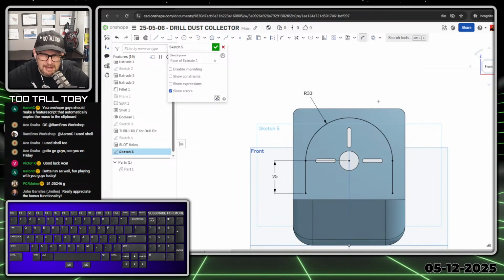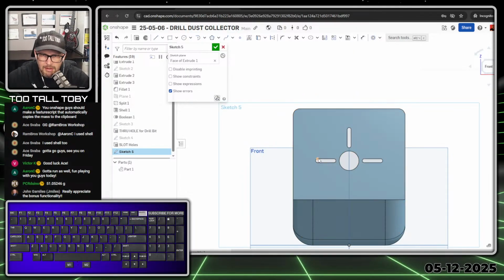One thing that I did there, I did it kind of quickly. Let me just show you this again real quick here. When I was creating that line arc line, I did the single click to begin the line, single click, move back, touch the end point, come up and over with the arc. And then I came down here, and then you'll notice that I'm not picking up on horizontal. This is a really good time-saving shortcut in Onshape.